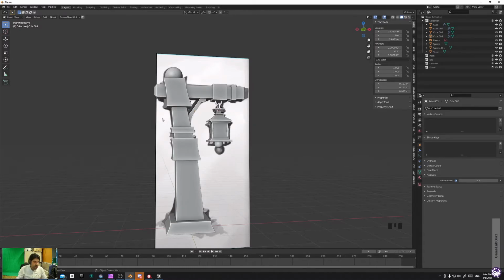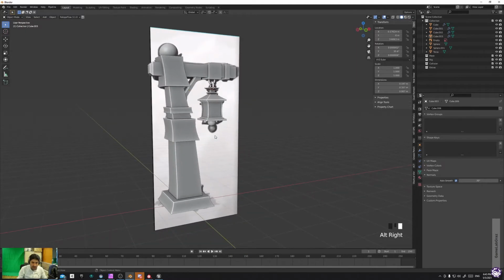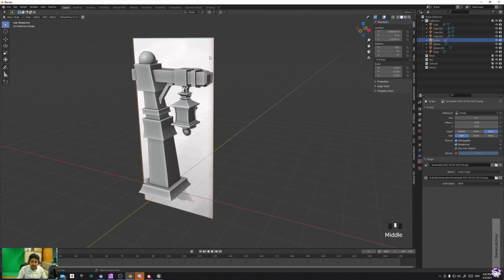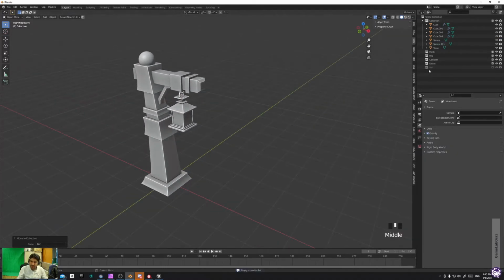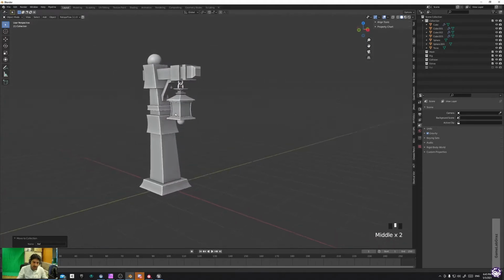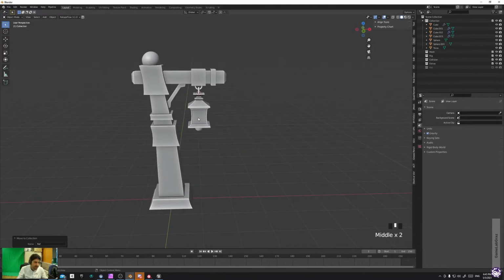Okay, then let's continue with the sculpting. I think I do not need this shape anymore. I know what I would like to do with the shape. I will just hide it. Or the other solution is to select part of your model, press M, and create a new collection. I will call it, for example, references, and then deactivate that collection. It's easier because I can add several things to that collection later if I need it, and deactivate them whenever I do not need it.